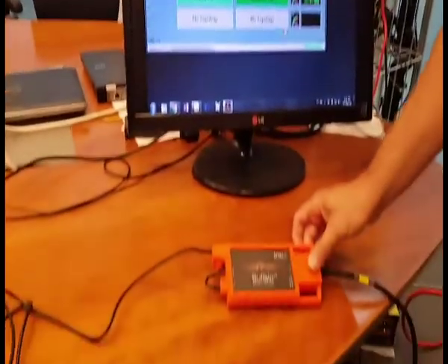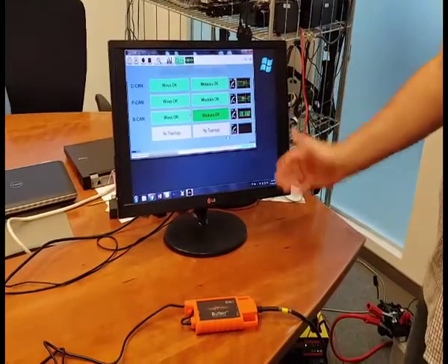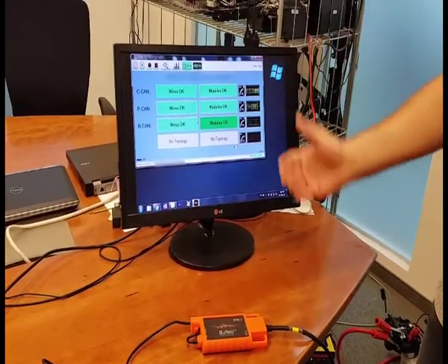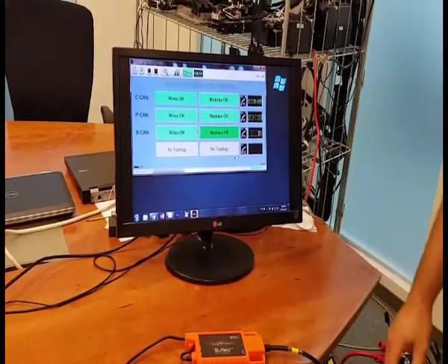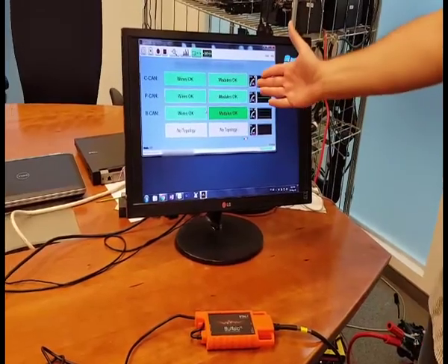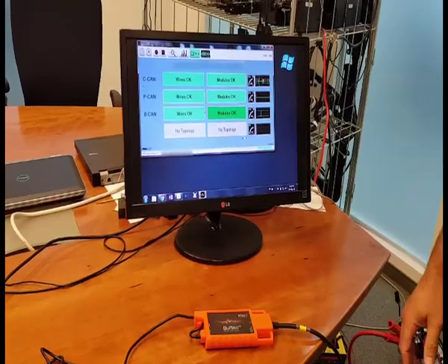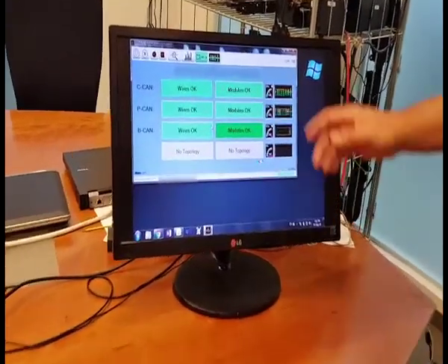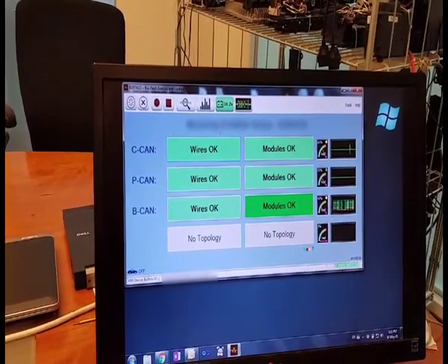The Buffalo equipment itself also comes with an integrated analog scope that enables you to monitor from a scope perspective complex issues that are not covered within the basic configuration of the Buffalo diagnostics capabilities. And this is more for an advanced use case. We also have live indicators for the bus utilization load, which can flash out various conditions concerning ECU communications on the bus, as well as indications regarding the network power voltage.